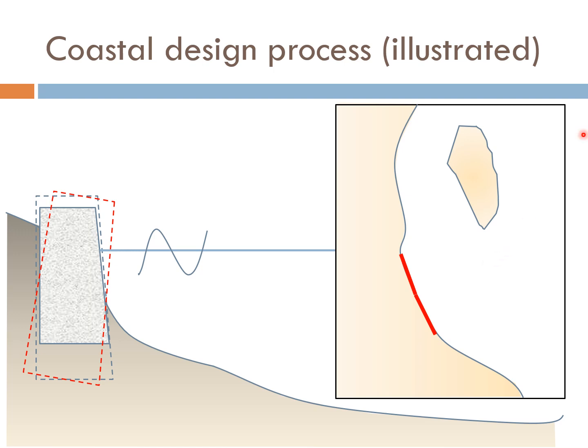Typically, offshore wind or wave data can also be used, but in order to find out the localized wave patterns, wave height, etc., the offshore information will have to be analyzed to give us the nearshore coastal climate. This can be done, as we discussed in the topic of wave mechanics, and this can be done using software as well.